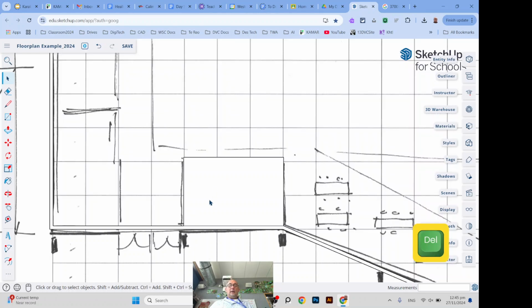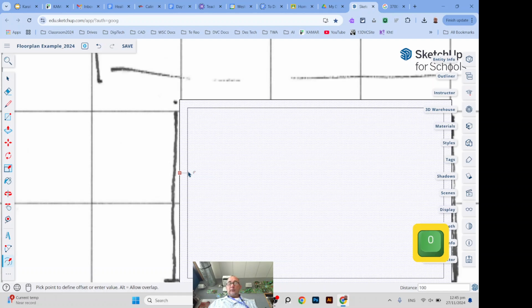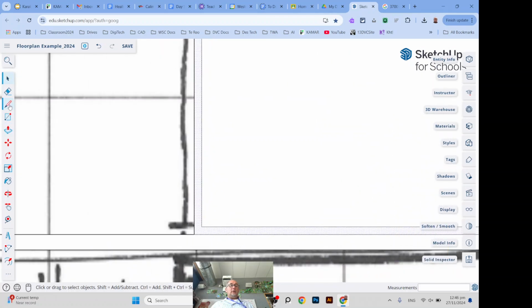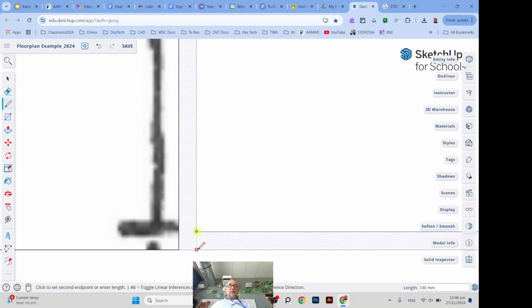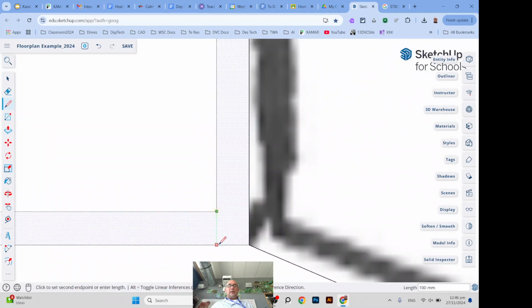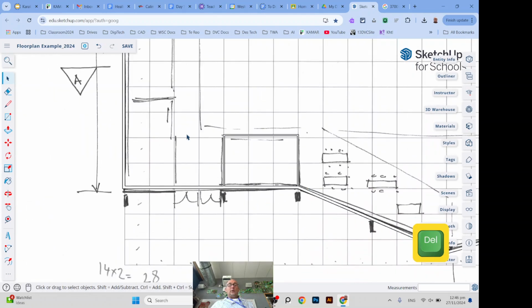We don't really want that. Now we can make some walls here. Again, use the offset tool. The last tool that you use, by the way, will turn up in this bottom section here. So we can use this again. Click once, move it out. These are interior walls, so it's going to be 100 mils. Press enter. Now you can see there's a bit of a problem. We can easily solve that by continuing this down to the bottom. Same thing here. Click there, down to the bottom, and then we can delete this line segment and delete this interior. Cool, so that's that part.